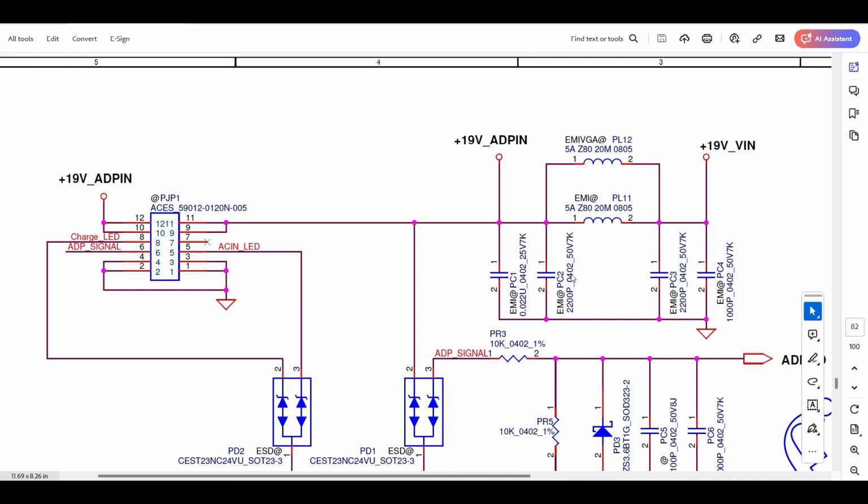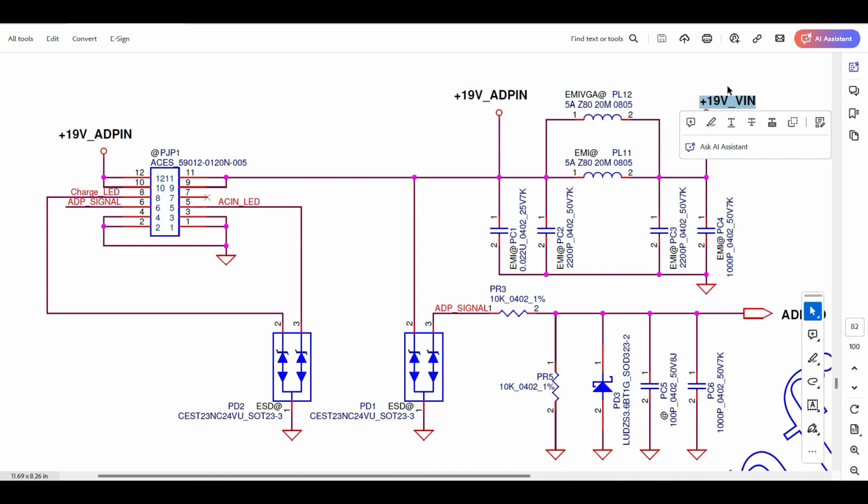So, here two capacitors for charging and discharging. What does it pass? It also bypasses. It will bypass AC and it will charge DC, and again it will pass here. When this power won't be available, then it will discharge here. So now through the coil it's a little bit of boost and we will get 19 volts V in. Here the main voltage we got; the second one is ground. Positive and negative, two parts entered.